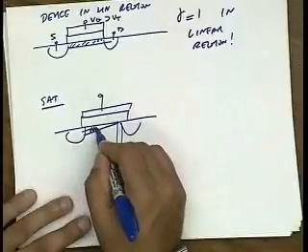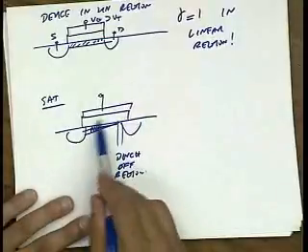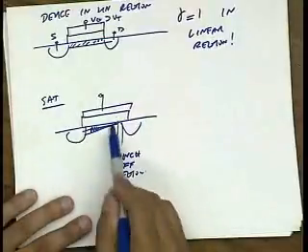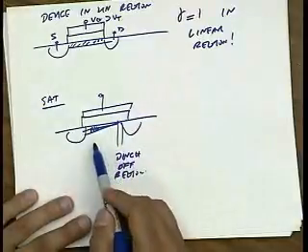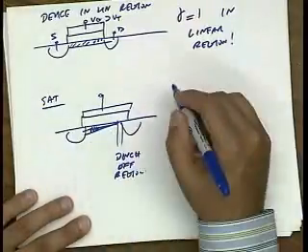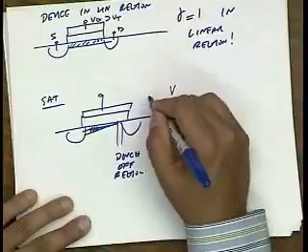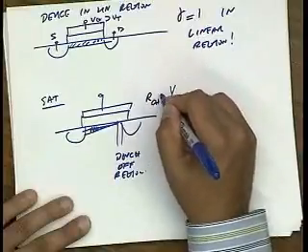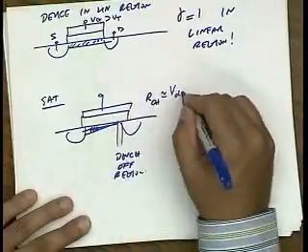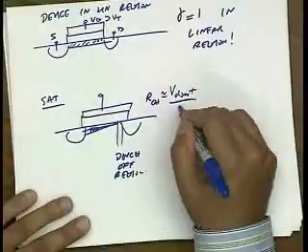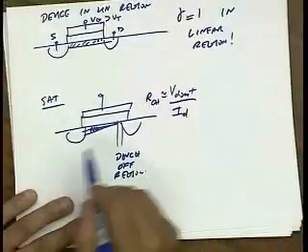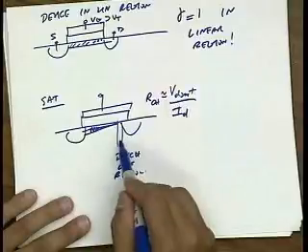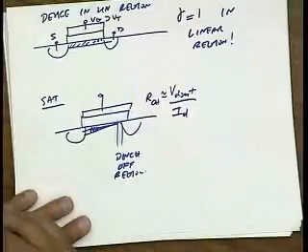But this resistance basically is the resistance of the channel. And this is the resistance that's generating noise. And this resistance of our channel is approximately VDsat over ID, right? Not VDS, because the extra VDS gets dropped across the pinch-off region.